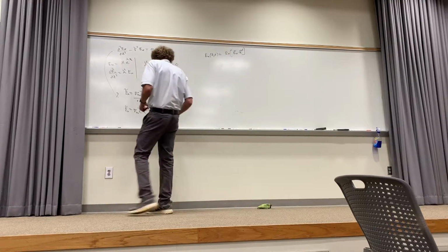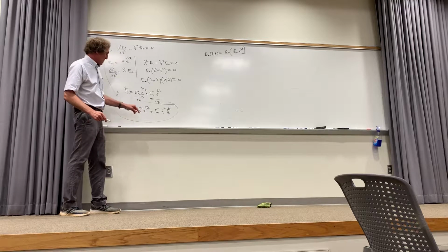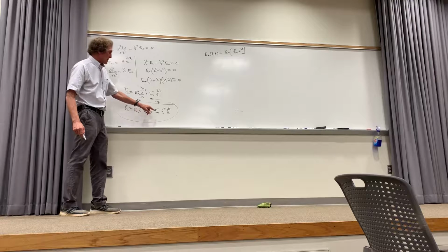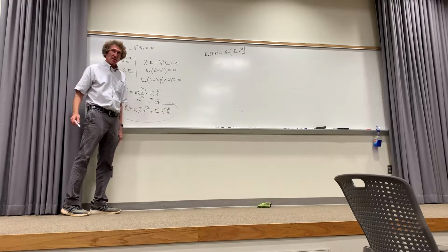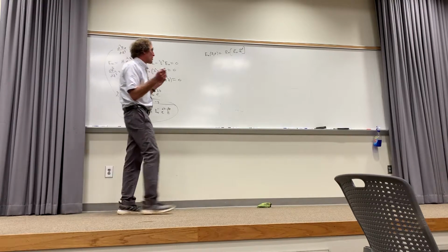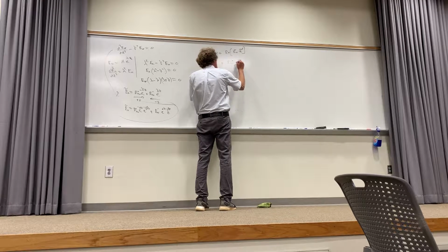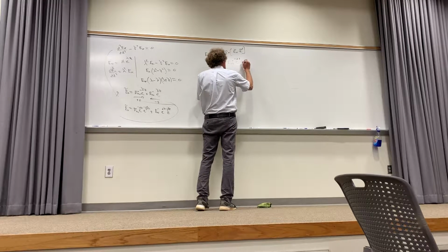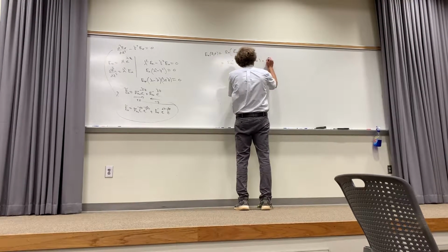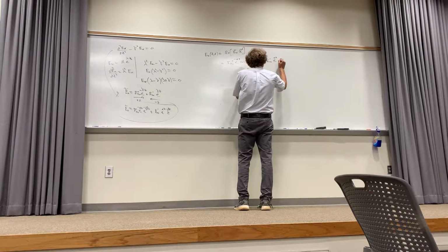Now, just take a look at this. When I multiply this by e to the j omega t and take the real part, the imaginary part here is minus j beta z, right? And the imaginary part here is plus j beta z. When I multiply those by e to the j omega t, they become a single argument, and the real part means I would get this. I would get Ex0 plus e to the minus alpha z cosine of omega t minus beta z, and I would get Ex0 minus times e to the alpha z